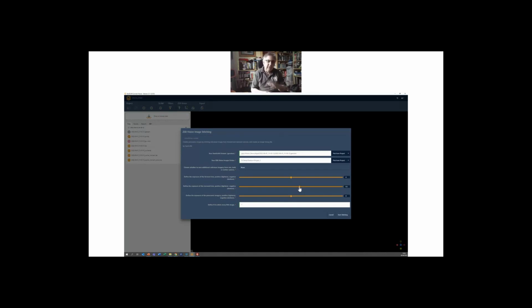So when we do the stitching, we get more of an equal exposure. There is some blending that goes on across the seam area to try and match exposures. But if you can see significant exposure differences between the forward and rear lenses, that's why you would use these two. Generally, you can leave them at 0. I wouldn't alter those too much. We will rectify the forward lens and apply any exposure settings here, then rectify the rear lens and apply any exposure at that point.